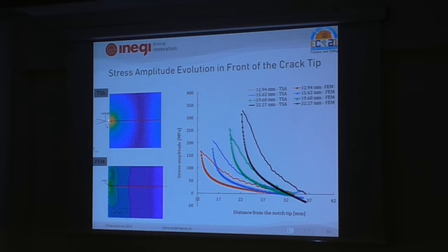This is the experimental stress ahead of the crack tip at a certain distance, and with thermoelastic stress analysis, to my knowledge, you don't get to see the traditional shape of a stress field. Yeah, but why is that different? Because one is calculated, theoretical, and the other is experimental. Or there's an averaging of the effect.